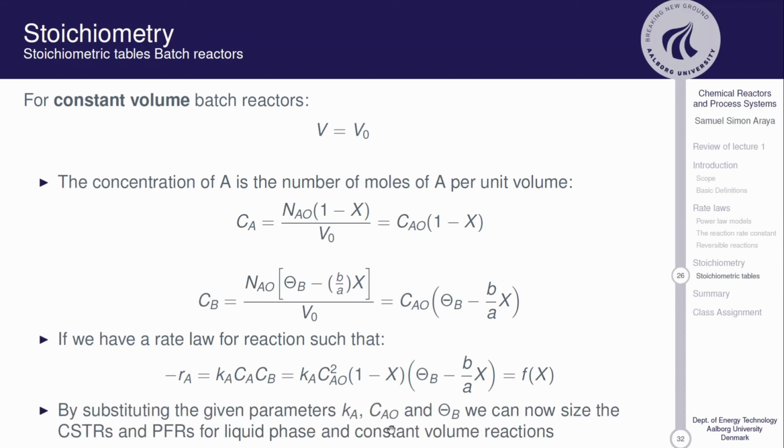And then by substituting these known parameters, we can size our CSTR and PFR using a Levenspiel plot or just by calculating the volume of the reactors.